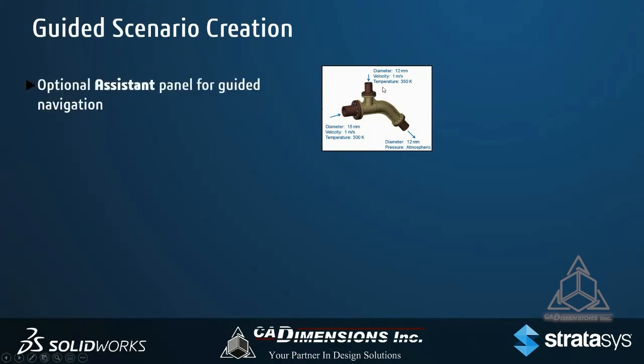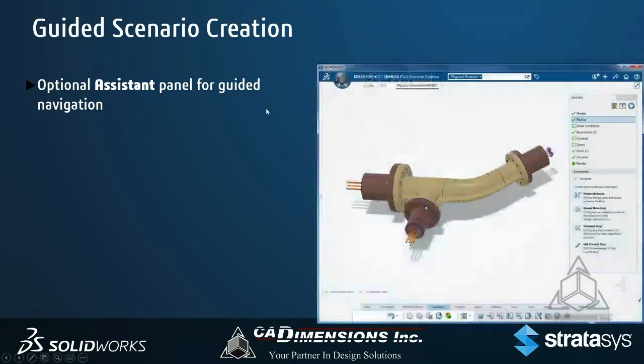The assistant in SolidWorks for the Fluid Dynamics Engineer, and this is not unique to the flow solution on the platform, there's an assistant as well for the plastics injection solution and the structural scenario solution. But the assistant panel is really, really nice. We got a preview of it in the video that I showed at the beginning of this PowerPoint, but what it really does is walk us through step by step, and it won't let us proceed until we have the step defined. So the first thing we need to do is specify our model.